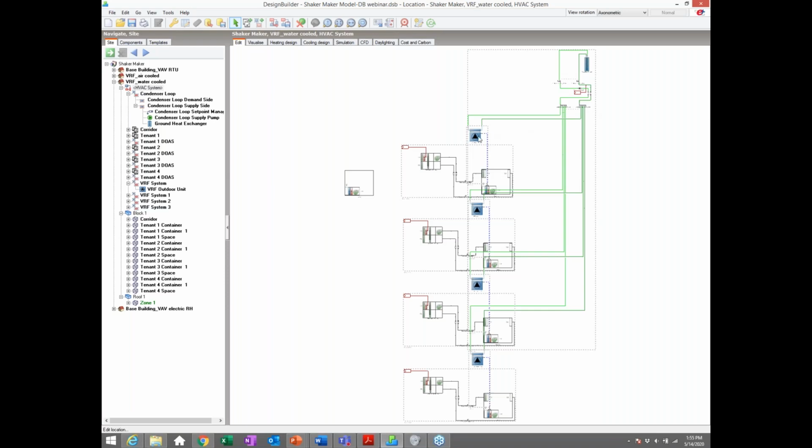The other thing is these outdoor units only go up to a certain size. So if you have a very large building, you might just run out of room, like run out of capacity on a circuit. So you need enough. So usually the occupancy profile or the size of the outdoor unit will be your determining factor for how to assign indoor units to an outdoor.